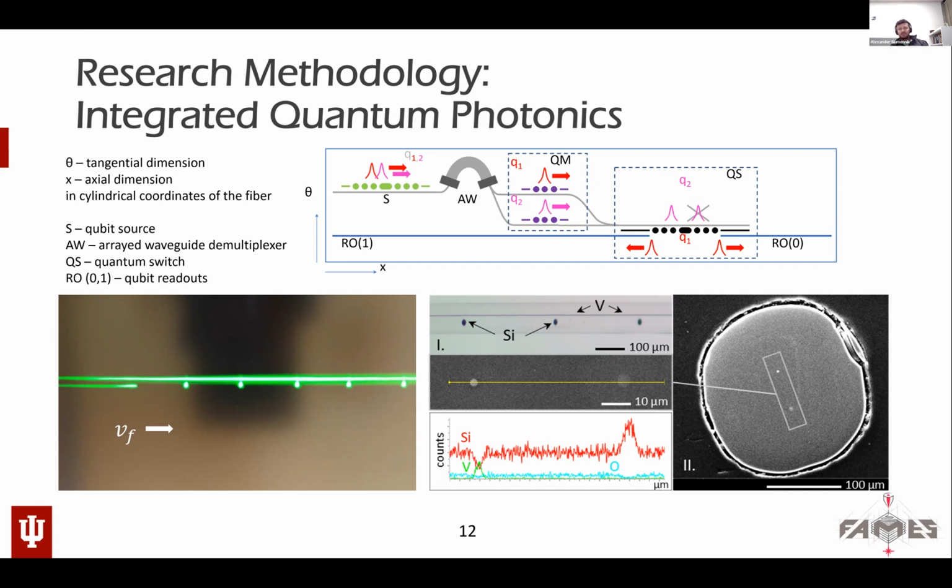So at the draw temperature of the fiber, which is 2000 degrees, it is liquid, so it is possible to draw into a core, but the breakup, which can be done anywhere above the softening point of silica, which is 1650, in that case, breakup is done at around 1800 degrees. So vanadium stays solid while silicon is liquid, and the silica around the silicon is soft enough in order to reshape when the silicon breaks up.